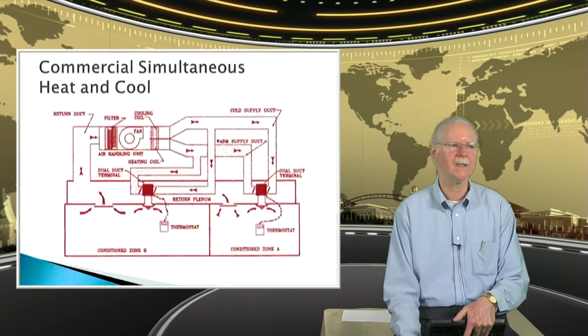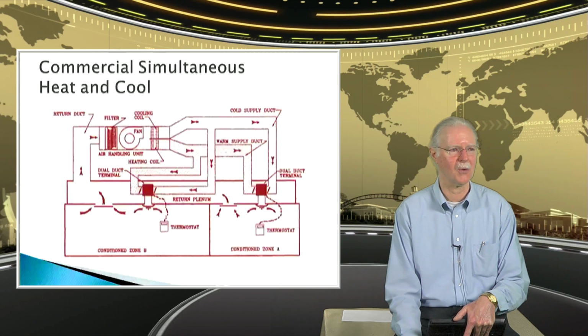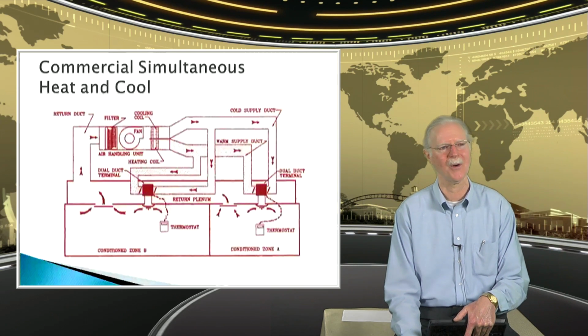The important point about this heat and cool at the same time issue is things go wrong. Is there a possibility that you're providing heat and cool at the same time and they're working against each other? Absolutely, it happens. And in those situations, you have a wonderful retrofit opportunity. If you can just fix the control system, it might be in the damper control, it might be in the control that actually sends the signal to tell the damper to open or close.